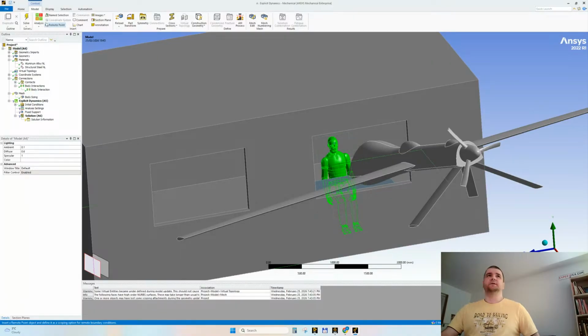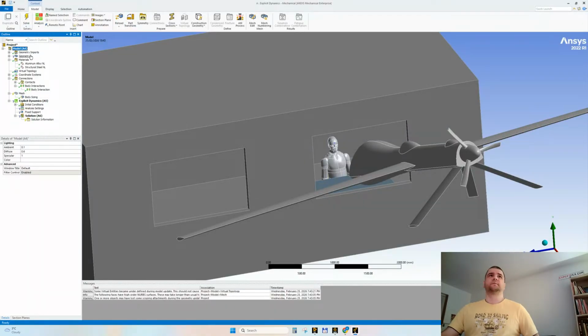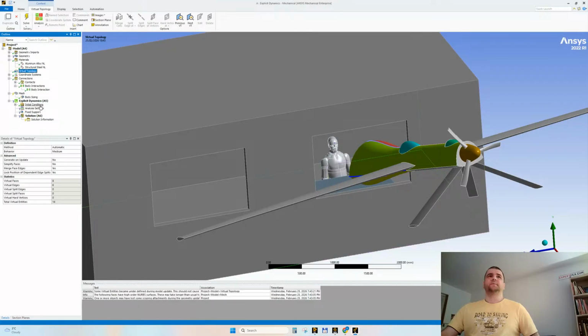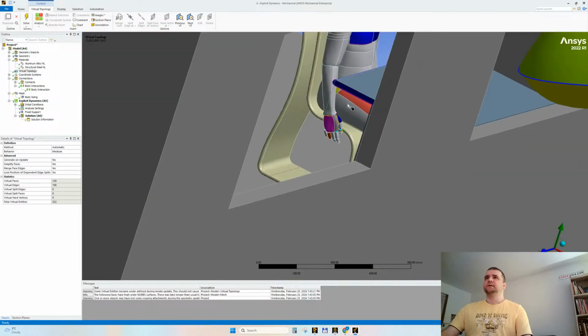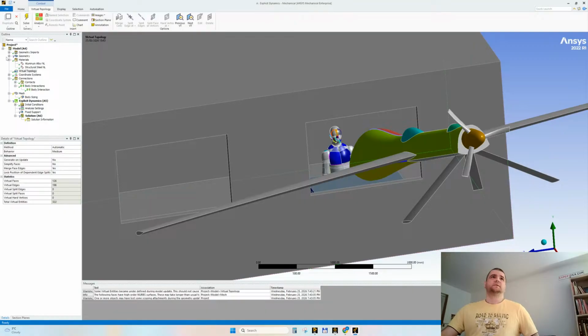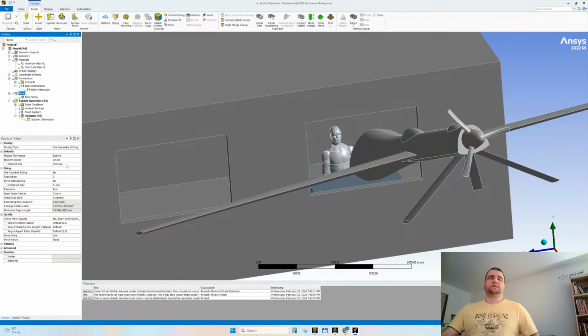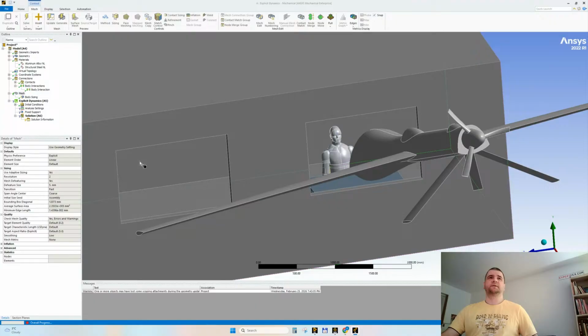There will be needed a virtual topology to unite the faces, also on the mannequin here. There are multiple faces there. Look here, yes. And also lots of faces. They were healed and united. And let's hope we have an easier mesh. If not, we will just delete it. We will just delete it now. 0, the feature size, maybe 5 here. I'm keeping this 100. Let's keep it. Why not?